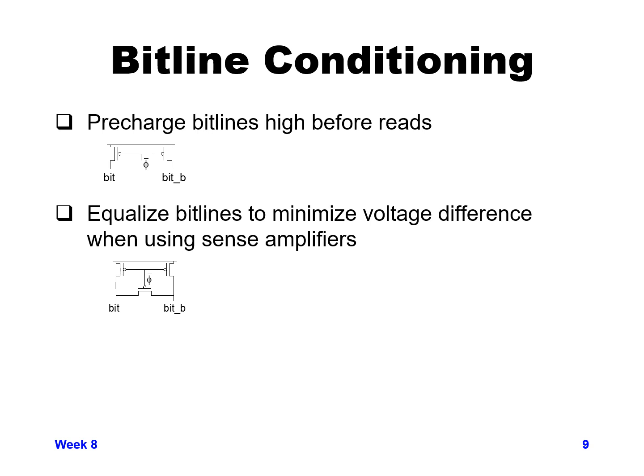We might not get it fully there. We don't want any differential at all on the two bit lines. One of the ways we can do that is when we first start pre-charging, in addition to pre-charging the side that was low, we turn on an equalize device between the two bit lines, and it will help pull the bit line that was high a little bit lower to equalize to the other one. Then as they're both pre-charging, they'll be closer in value to each other and hopefully almost exactly the same value by the time you finish pre-charging and go into the next cycle.